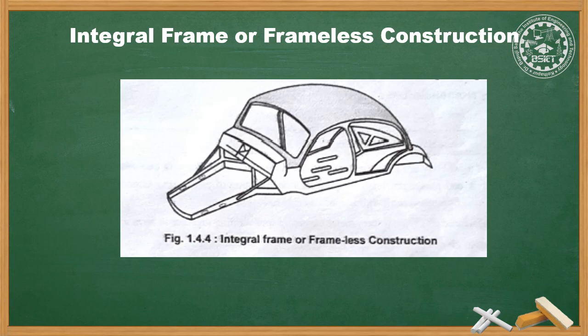as it has advantages such as lasting longer, that is increased beam strength, adequate torsional stiffness, requires fewer parts, involves fewer assembly operations, more economical weight reduction, that is more economical, reduced weight, improved fuel consumption, longer life, and in integral construction the reinforcing members are provided below the floor, so it does not occupy space.